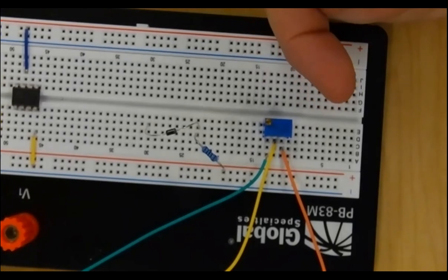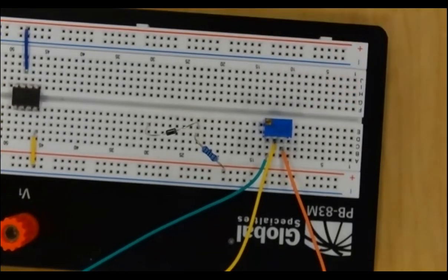Okay. So the input voltage varies from 1 to 4. Sorry, the input voltage that we put through the pin. I was asked, what is the input voltage? The input voltage of these pins can be 0 to 5. That 1 to 4 was just a particular example. It's not going to be exactly 0 to exactly 5. It's going to be a little bit more than 0 and a little bit less than 5.